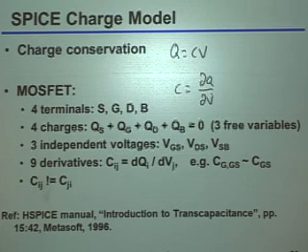voltage. Okay? And by the way, when you specify the change in charge, they even mean the change in charge at a particular node relative to the change in voltage. Okay? So if you think really carefully about a MOSFET, there's 4 independent terminals, right? There's a source, a gate, a drain, and a body. So from the standpoint of voltage, that means there's 3 independent voltages you can define. Because remember, voltages are always relative, right? So there's 3 independent voltages that you can define between those 4 terminals.